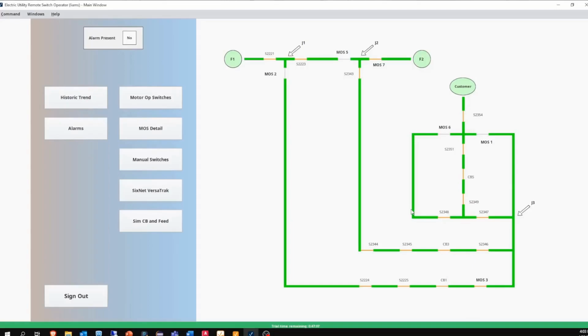When users get to the main operations window, every user will see the current status of substation circuits, but their access to monitoring and control functions through the navigation buttons depends on the security role assigned to their user account at the ignition gateway. The predominant graphic feature of this HMI is the substation status diagram. In order to show which conductors are currently energized, I created tags within the HMI design application that use Boolean logic applied to power feed states and switch states.